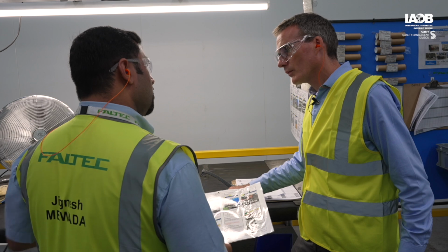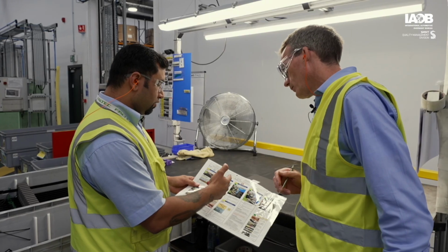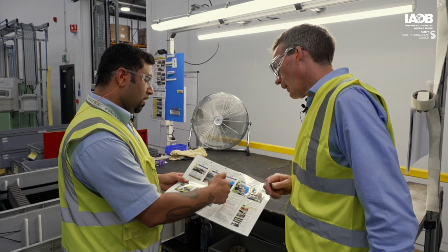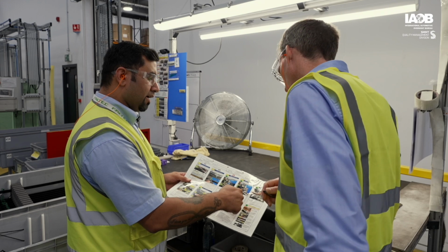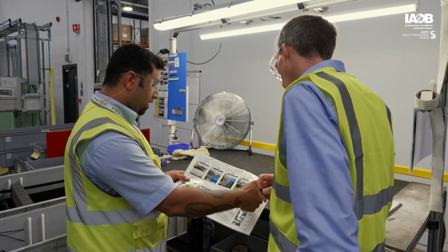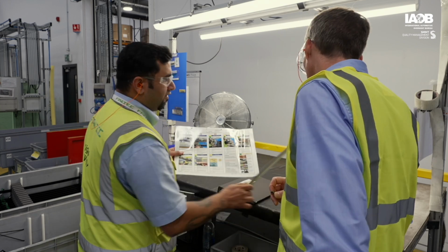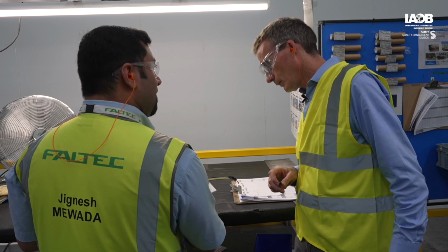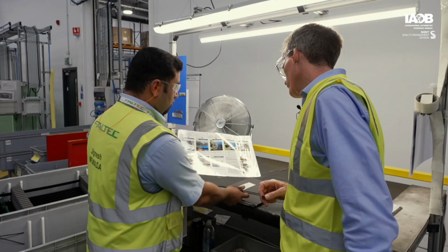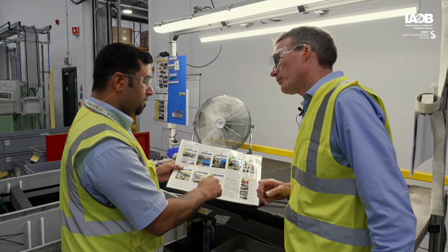You pick the part out from the box, and put it back when done. Step by step, you get a part out and check the tapes are all right. You visually check the A face of the part, and the B face of the part. You check the end caps are all right. You check there's a tape present, to make sure the tape is there. Then push the end cap like we did, which is the test. So we push the end cap, then stamp your identification on the label, and that's it.